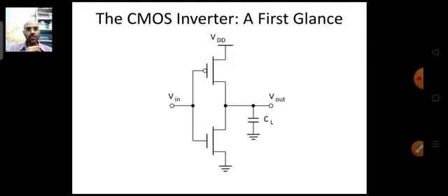Basically, we have seen how an inverter will look, and what the various voltages are in the inverter VTC. Okay, because this VTC which we have plotted is the DC characteristics of the inverter. When we see the DC characteristics, the important voltages are VIL, VIH, VOL, VOH and VTH. These are the 5 important voltages which we have seen yesterday, along with their definitions.